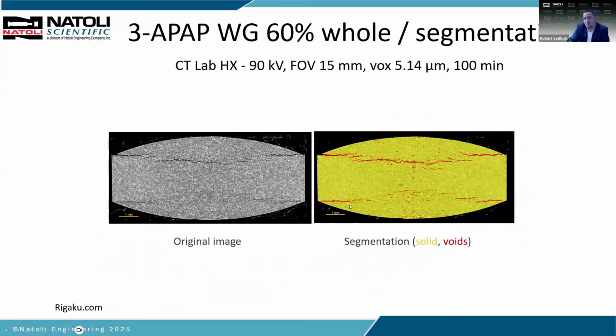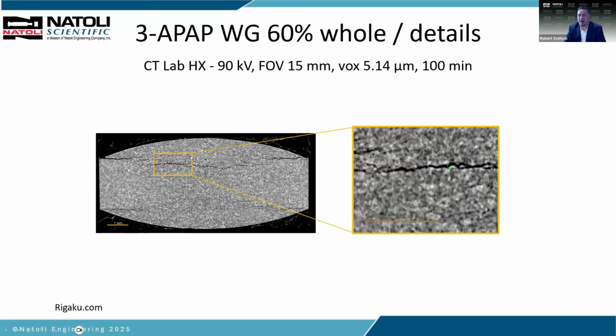Last thing I want to mention here is CT scanning and X-ray. It is something we can use to look inside the tablet for density variation, micro cracks. So for example, this has a convex cup, and you see the micro cracks right at that area where the belly band meets the convex area. That's a density variation. So reducing the cup depth on your tablet design can reduce capping issues. So something else that Mike can do in his program here. Again, micro cracks, density variation, foreign materials, contact uniformity, and so on.